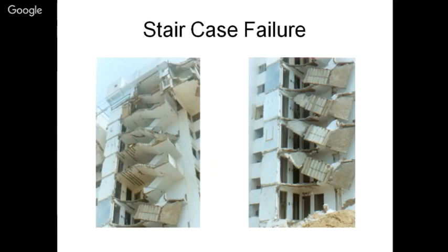Staircase failure is the first and foremost failure in the case of a structure. The reason is that the staircase is a little bit vulnerable structural element in an RCC structure as compared to other structural elements. So in case of an earthquake, it behaves as a fuse to your structure.